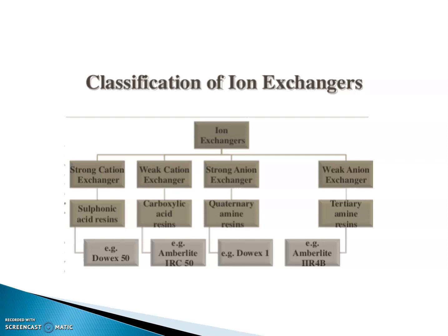Weak acid cation and weak base resins, particularly Amberlite IRC 50, are able to neutralize strong bases and acids respectively. These resins are used for dealkalization. The concept of dealkalization is that the system should remove the alkaline material present inside the system, that is, material responsible for exhibiting pH greater than 7. They are also used for partial demineralization, or in combination with strong resins, full demineralization.